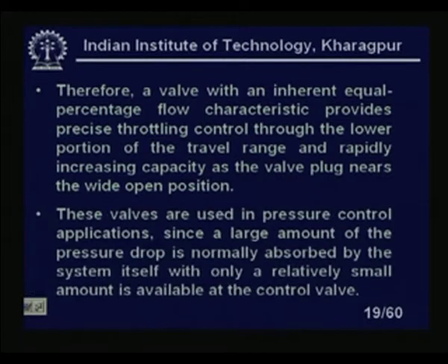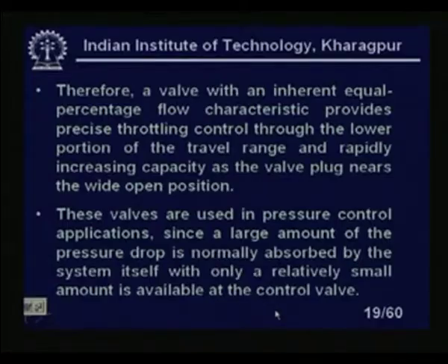Clear? These valves are used in pressure control applications, since a large amount of the pressure drop is normally absorbed by the system itself, with only a relatively small amount available at the control valve. There are various kinds of applications. As I told you, for pressure control, this type of equal percentage valve will be more acceptable.